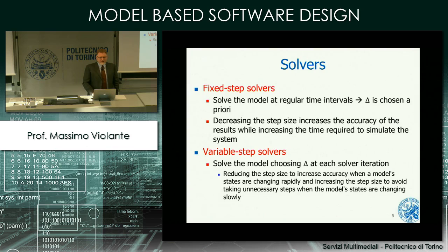So what is happening here is that Simulink analyzes the model before starting the simulation, and tells which is the value of delta to be used through all the simulation, in case you adopted auto as a configuration parameter. Otherwise, it sets delta to the value that you specified, and then that value is used in any time instant of the simulation.